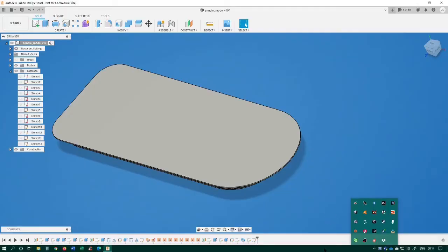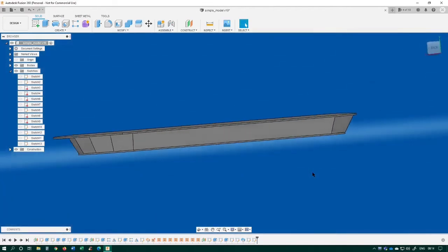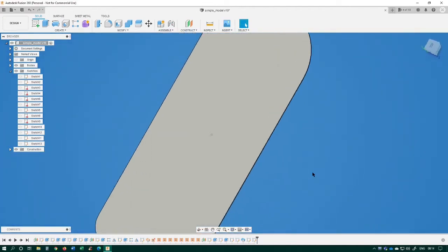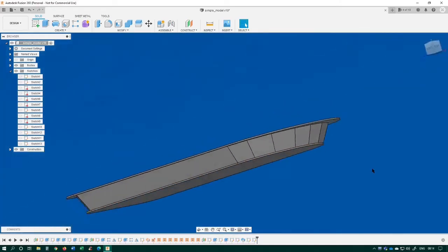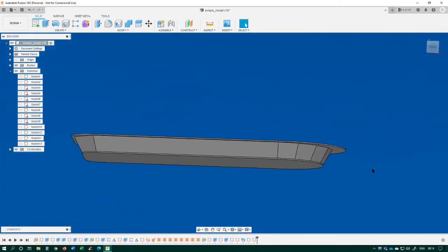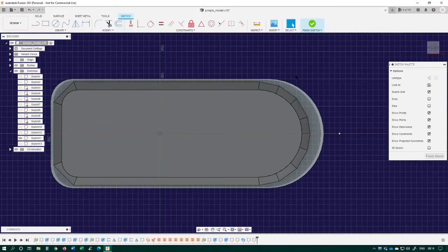Now this process will work for most hull shapes, but if you have a curved plan shape, you'll need to create an approximation line on your model made up of straight sections before you create the surface sweep. This ensures that the skirt sections remain flat in the lateral dimension, which is important to enable successful flattening in Meshmixer without distortion.